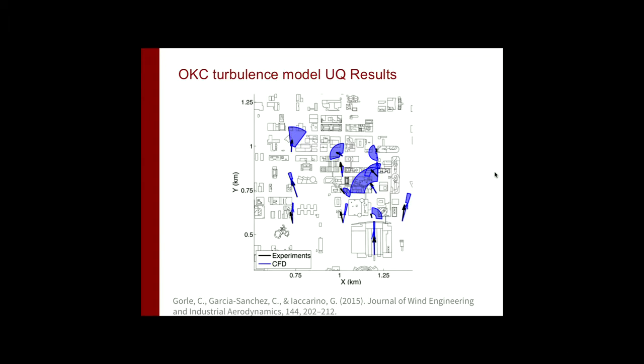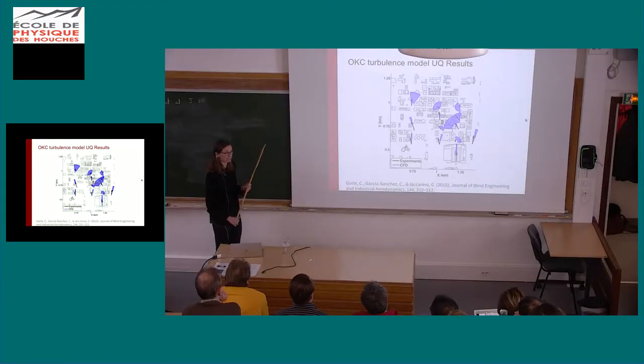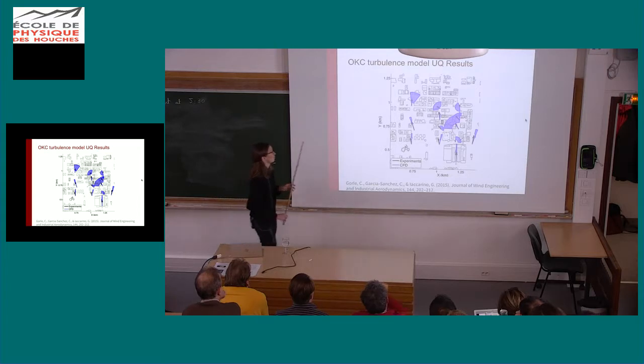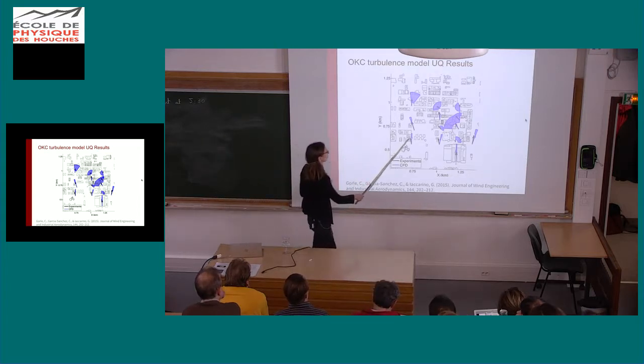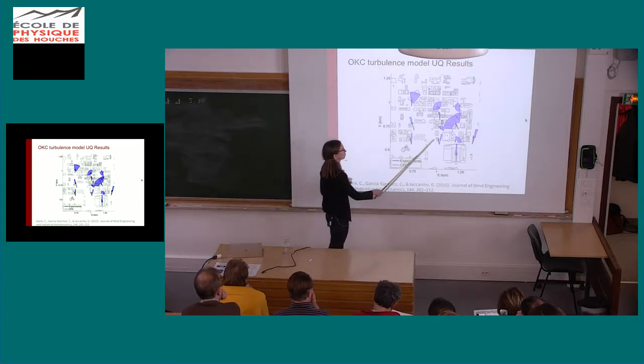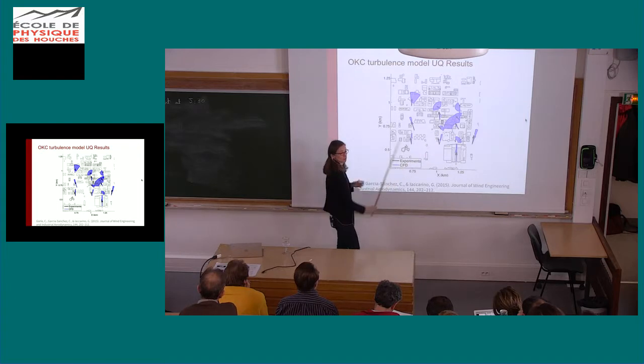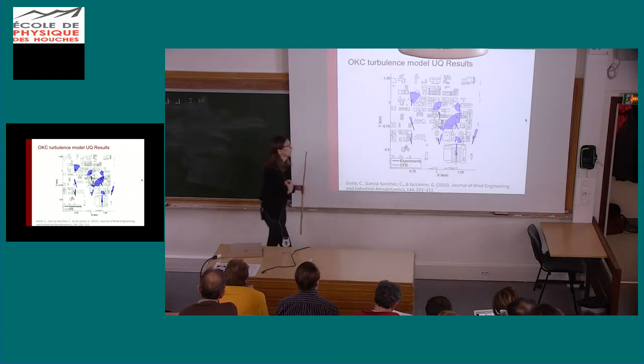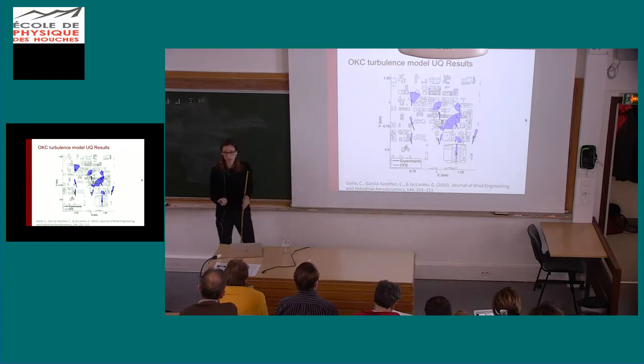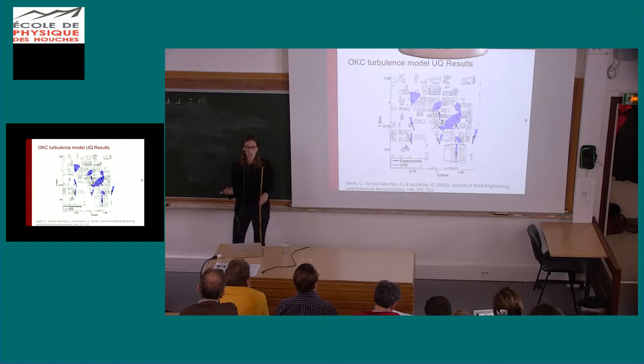There is really not a way to validate this well, but you do see something interesting, and that is that it seems to indicate regions where we have very small uncertainties because of these turbulence model assumptions, and regions where these uncertainties are much larger. So again, for an engineer who is running a RANS simulation and is scratching his head, like, how much can I trust this result? This is pretty useful information, right?